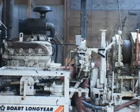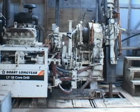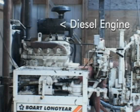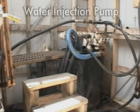The components of this system are designed to be broken down into 1,200-pound modules to facilitate transportation into remote areas. These modules or components include a diesel engine to provide power, the drawworks, which facilitates tripping in and out, the swivel head to provide feed and rotation to the drill string, and the water injection pump to assist with the flushing of the cuttings and the cooling of the drill bit.